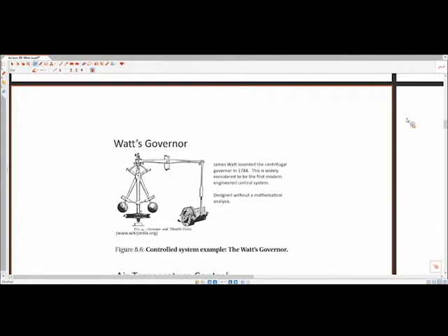Was the mechanical system controlled by a person, or was it based on the fact that if they were going on a decline it would speed up, so the system would close to slow it down? So I imagine there were probably set screws or other things to adjust it, but it's all self-regulating. So the idea is that the speed is directly transduced to this rotating element, this centrifugal governor. And so regardless of whether you're going up a hill or down a hill, right, you want a certain height of the balls going out, right? So that changes then the throttle position.